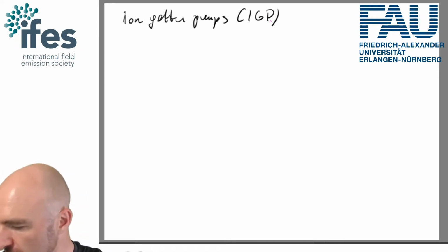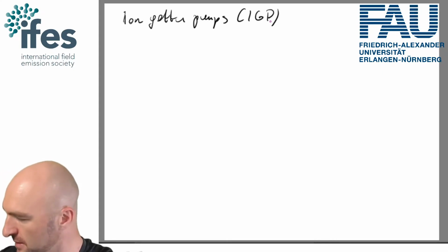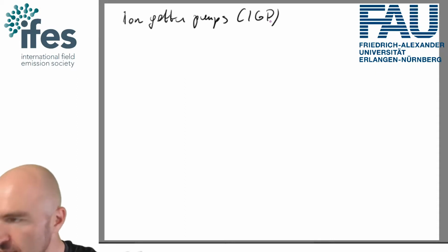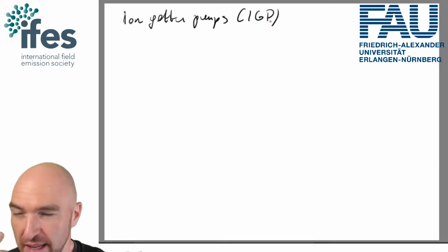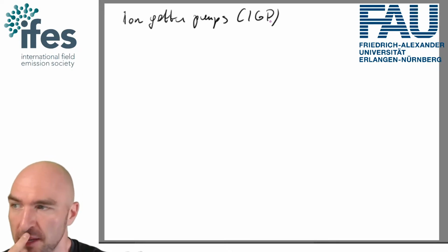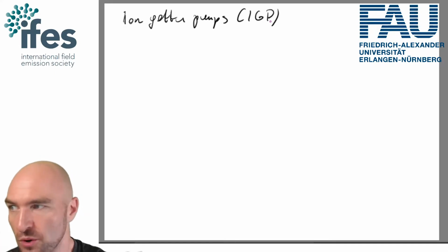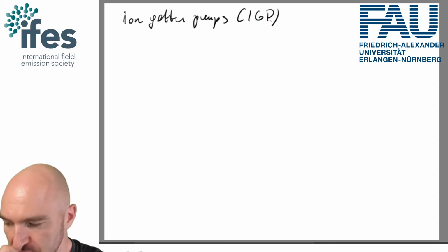And so essentially what we have here is an anode and a cathode. We have a system where we do two things. First of all, we ionize any gas that goes into our system, or we ionize part of the gas that goes into the pump, and use that ionized gas to sputter titanium or titanium tantalum combinations, some reactive metal. Usually it's titanium, but it might not be pure titanium.